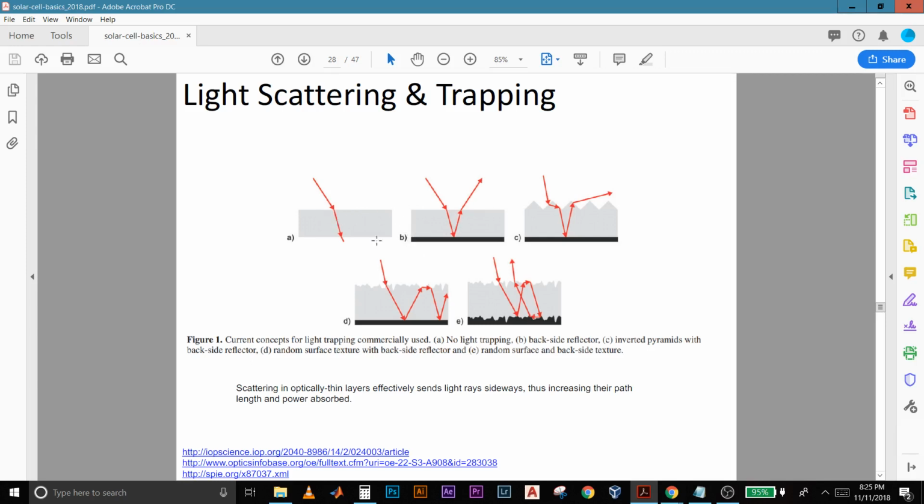The first thing we can do is simply not allow it to go out of this device by putting a reflective layer on the backside. So if that is the case, then the photons would reflect off this reflective layer and at least firstly have twice the time that they remain inside the slab. So from here to here and then back up here. Then they can escape from the front surface. Now obviously we can place another reflective layer, then we would not be able to have incident photons entering the slab in the first place.